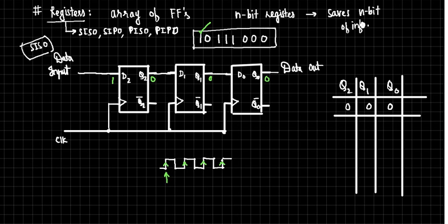But what takes as an input to the second flip flop, that is still 0, right? And for this flip flop it's still 0. I mean that 1 which was transferred from the input is only captured here, because as all three of them are being synchronized, they will receive the previous output. So this will get transferred here, this will get transferred there, and this will get transferred there. So it's like a shifting which happens. The data is being shifted.